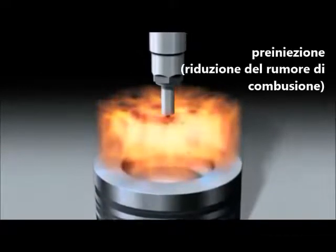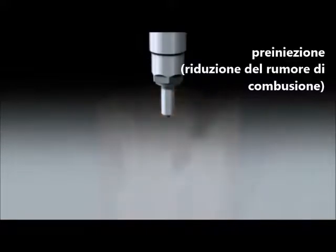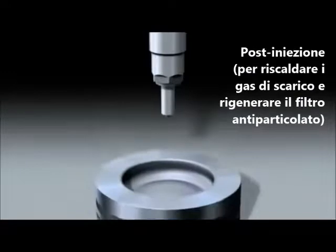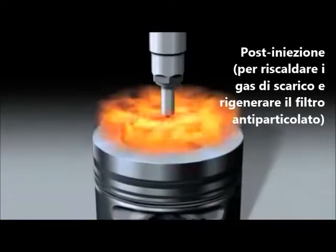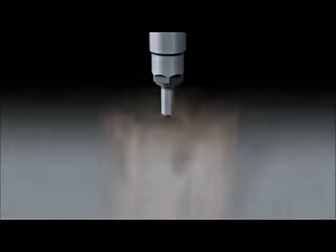Pre-injection moderates the acoustic hardness, the so-called rattling of the combustion process. Post-injection is specifically to raise the temperature of the exhaust gas and therefore for regeneration of the standard diesel particulate filter. These factors together allow exact, highly efficient combustion.